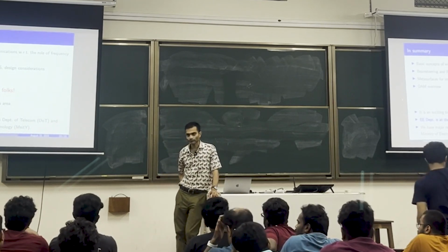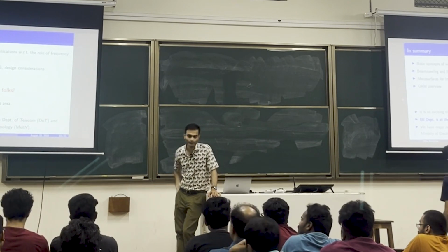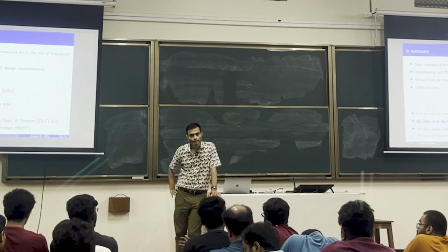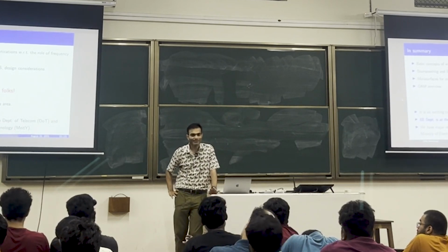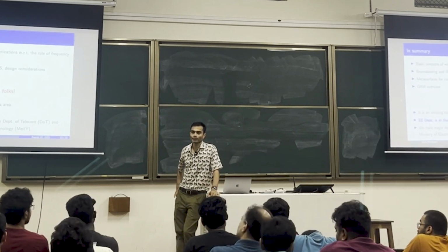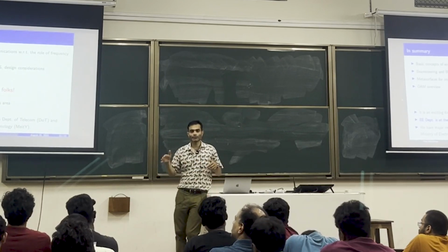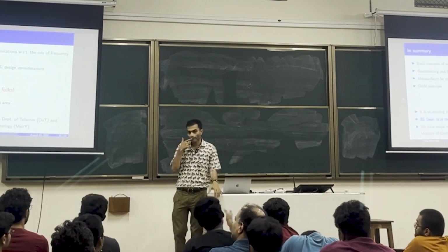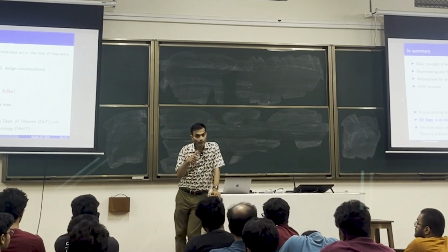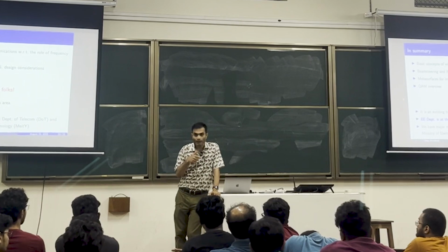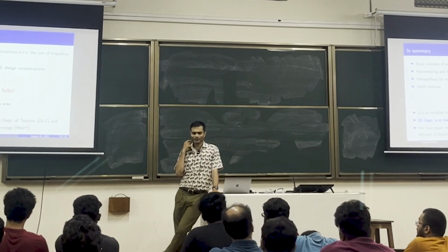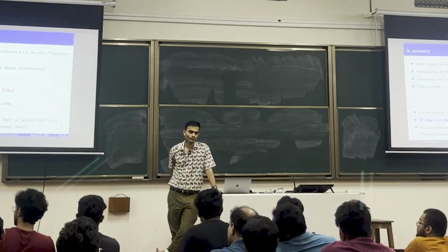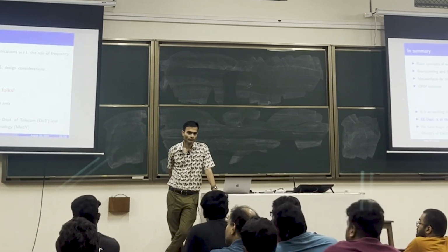Correct, on the train, and that could be at a higher frequency. So we are assuming the RIS speaks to the base station. To some extent it's not possible for there to be no communication, some kind of a wireless link. Because the base station speaking to RIS is one. I'm talking about RIS speaking to the base station. That need not be. But then, if there is no LOS, the base station doesn't know where the user is. It's the job of the RIS to tell where the user is.